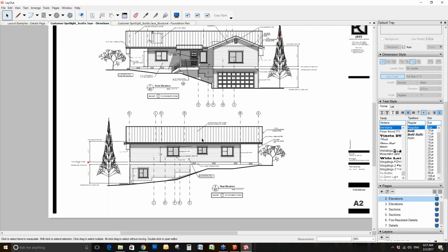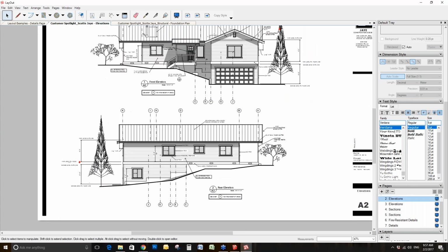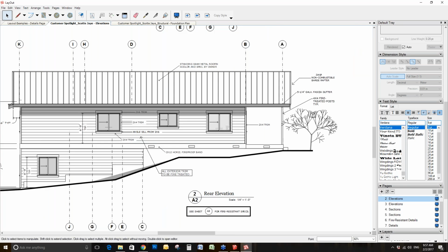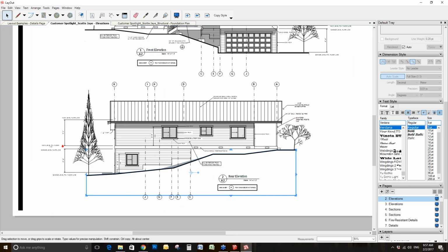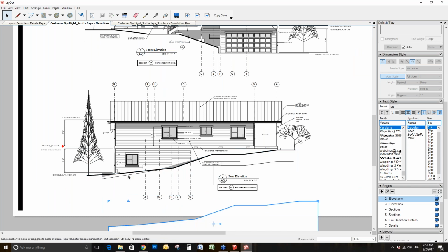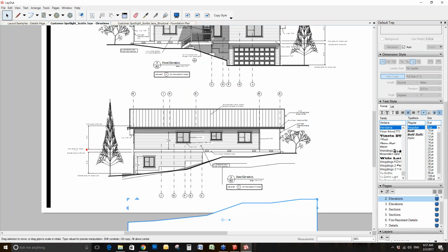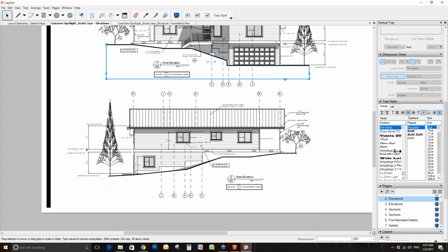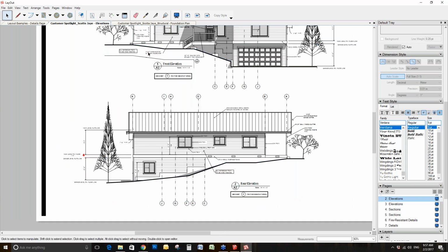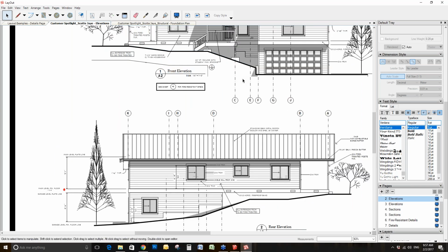Elevations, same thing. How do you set up elevations? You set them up with a masking layer. The masking layer is very important because in your PlusSpec and your SketchUp model, you're seeing through. You haven't set up an actual solid part that is going to read as your site. So it gives you the ability to hide the parts of the model that you don't want shown.